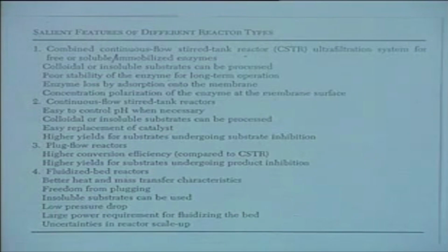Now, in the case of long-term operation, the system undergoes a very fast rate of deactivation, mainly because you have to transfer the whole material along with the substrate into the ultrafiltration module and recycle back the retentate. So during all that transfer there is significant loss occurring, and as a matter of fact, you must also appreciate that one of the reasons of inactivation is also shear inactivation.